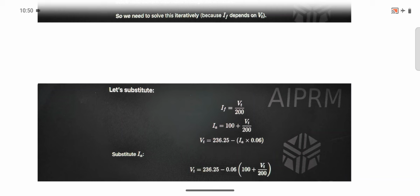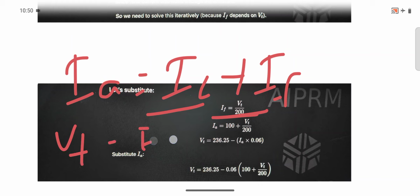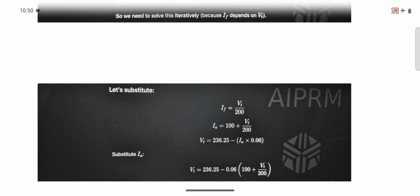Armature current, how do we know? Armature current is equal to IL plus IF. IF we calculated from the formula, and IL is given, 100 ampere. So we will get IA. Now terminal voltage we calculate as E minus IA RA. Then we will use this formula here and we will get terminal voltage.